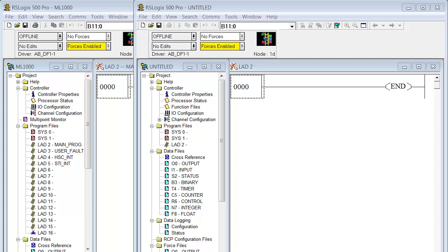Now, one thing that I want to reiterate here, when we were talking about baud rate, when you are working in the realm of Micrologix 1100, really when you're working in the realm of any development software with a PLC, the baud rate resides in three locations.